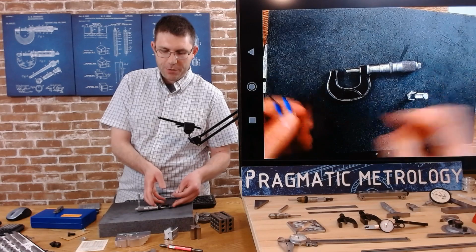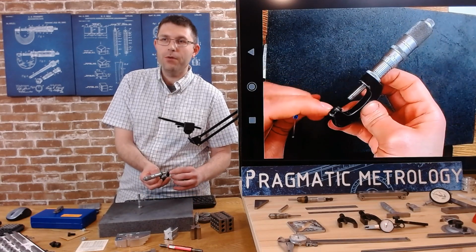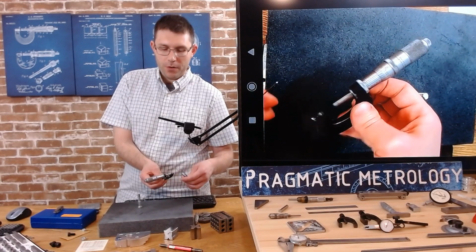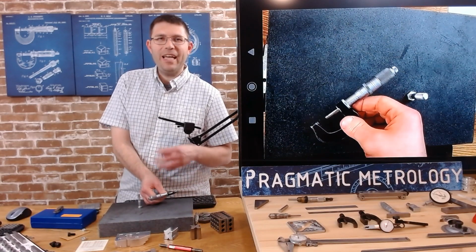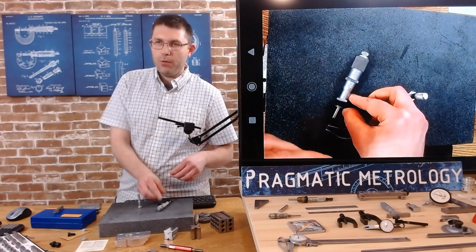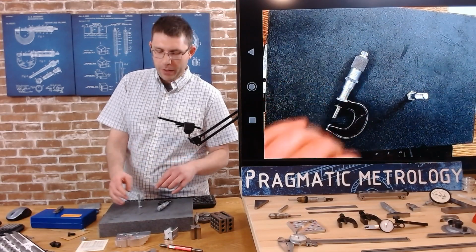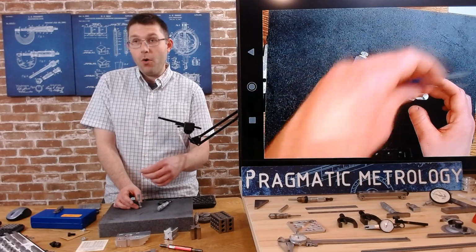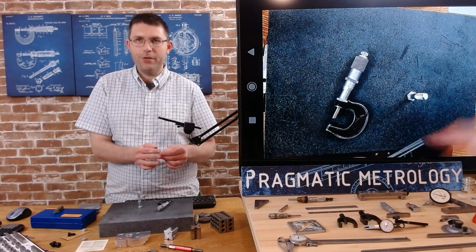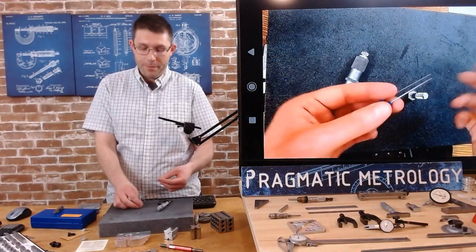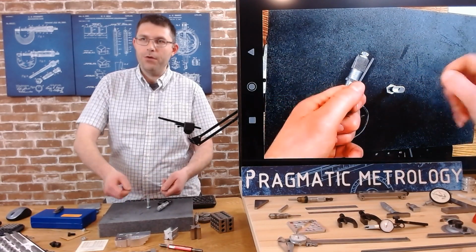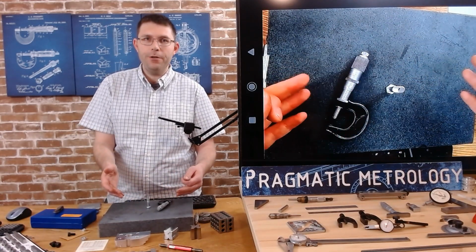There's attachments that you can snap onto your micrometer to hold the wires for you. I've seen people use those. You can use like a heavy grease. A grease will kind of push itself out of the way when it comes time for the micrometer to make contact, but it will hold the wires. If the wires are light enough, it will just hold them in there, so you can put your grease and your wires on and then come across with your OD mic and don't need to hold anything.